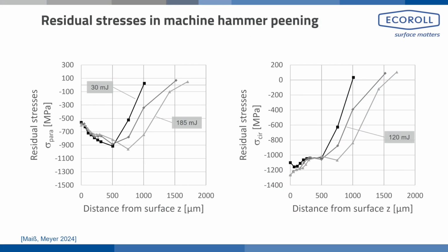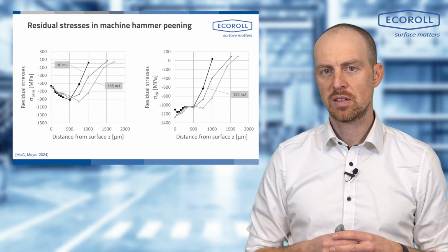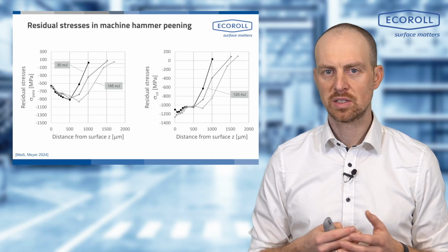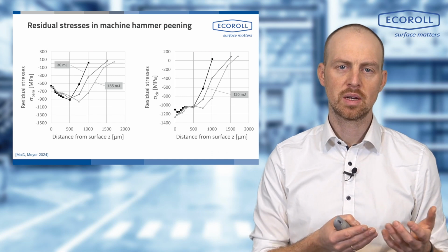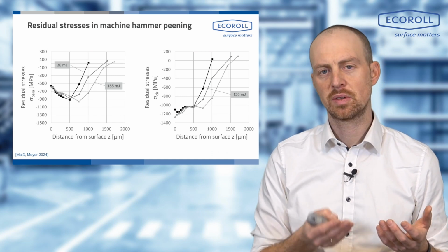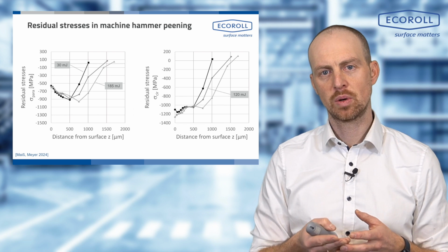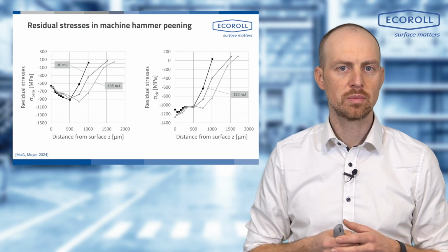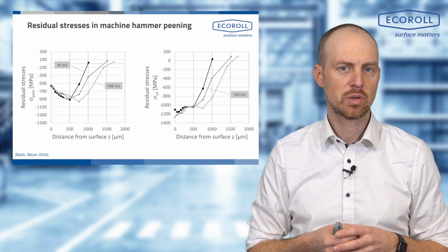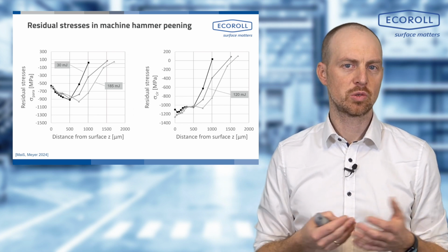The most essential reason for hammering is always hardening. With hammering, I have impact energy, I have significantly greater deformation, I have an impulse effect, and this leads to significantly more compressive residual stress than in other processes. The compressive residual stresses generated during hammering here are similar to those produced during rolling. I have compressive residual stress on the surface, which usually intensifies a bit more and then approaches zero at some point. The difference from deep rolling, however, is that this occurs at significantly greater depths.